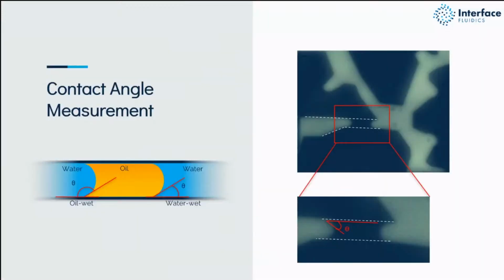Here is how we measure the contact angle, if you are interested. We take high resolution optical images in the frac zone because there's better optical access to the interfaces of the fluids. You can see in this picture, which is the actual picture of the process, the bright, greenish color is oil, and the non-oil phase doesn't show here because we use fluorescent microscopy. So we can clearly show the interface and the meniscus of the system, and by drawing the tangential lines, we are able to measure the contact angle.